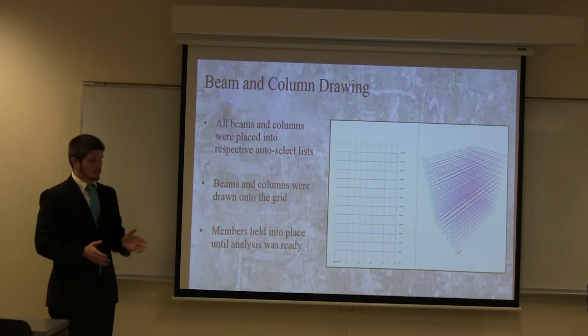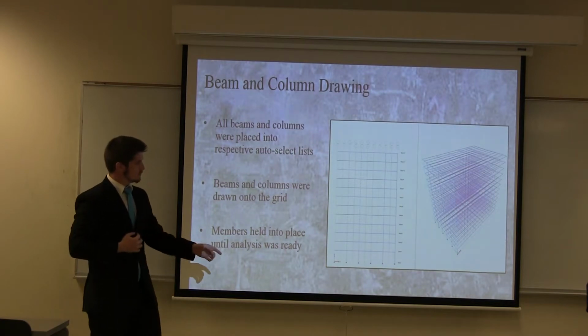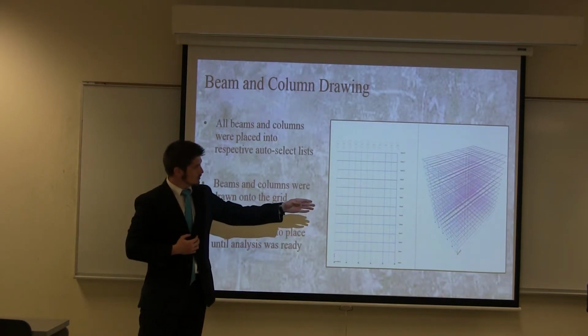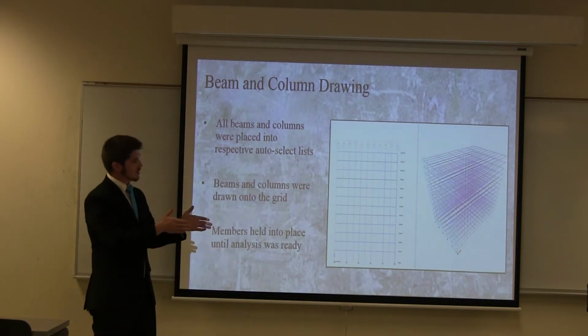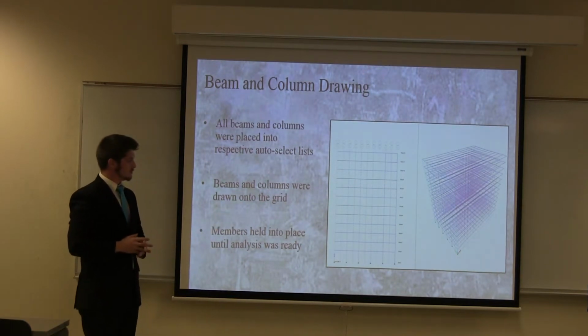We placed the beams 10-foot spacing apart, and then they were 20-foot long. The short direction of the building had the 10-foot spacing of the beams, and the long direction had the 20-foot spacing of the beams.